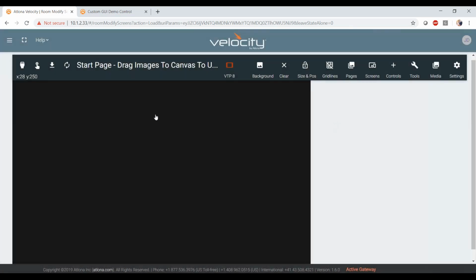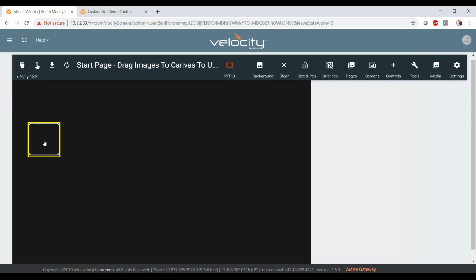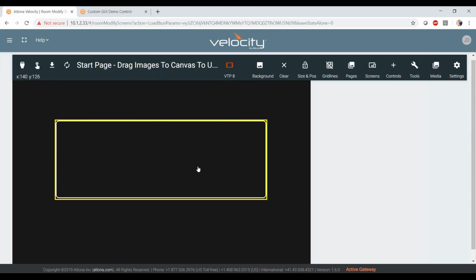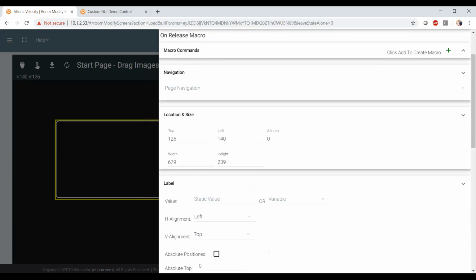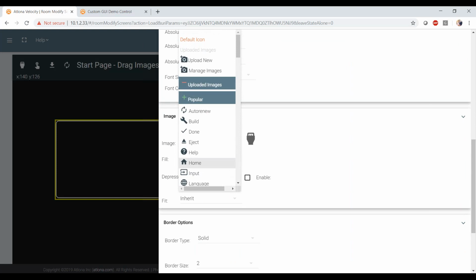And again, what it does is automatically take the background that we've given the standard GUI pages. So again, flat black here. What I want to do is add an image, but in this particular case, I want to have the ability to size my image as well. So the way I'm going to do that, and I apologize, this is a bit of a funky way to do this. I could have just created a background and used a picture background, but what I'm going to do is use a button, and I'm just going to add this image as the image for the actual button here.